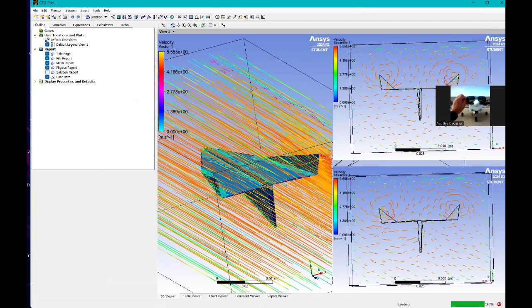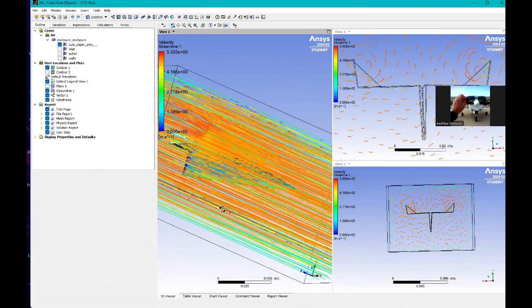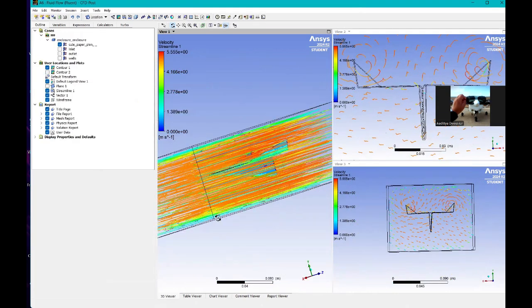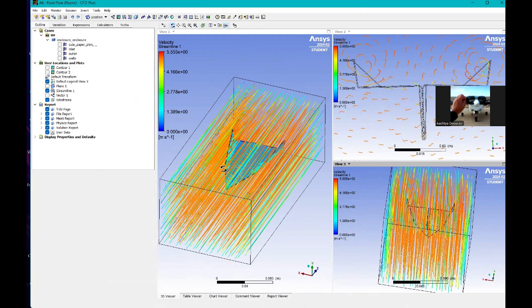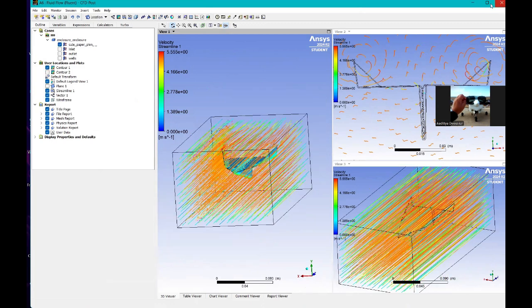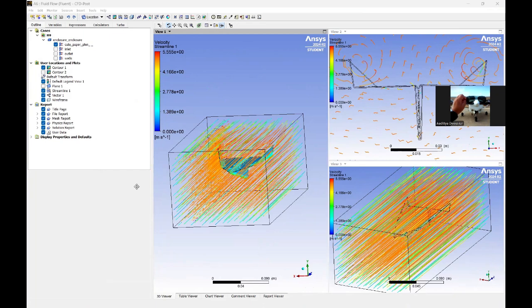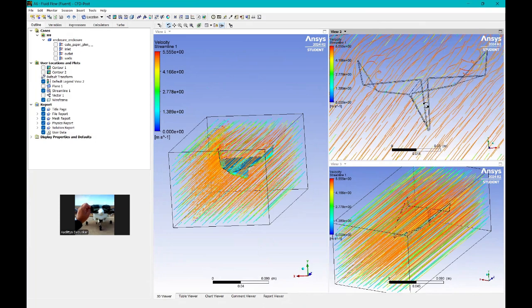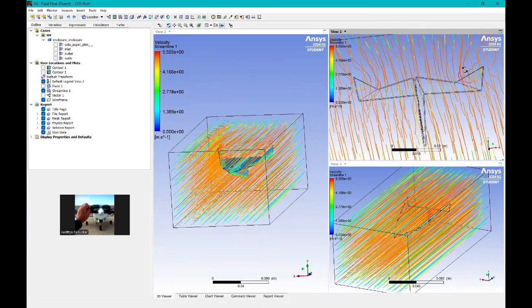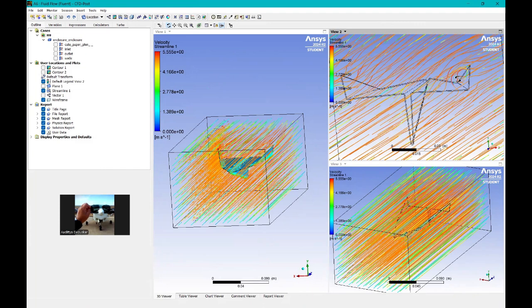After the simulation, after our solver has done its work, after we have incorporated all the factors, we get the following simulation results. So this is the same airplane. As you can see here, these are the velocity streamlines across the paper airplane. This is the vortex generation. As you can see, velocity vortices are being formed because of the tips. And usually they happen in aircraft as well. They are known as wingtip vortices. So, wait a second, let me just turn it off.